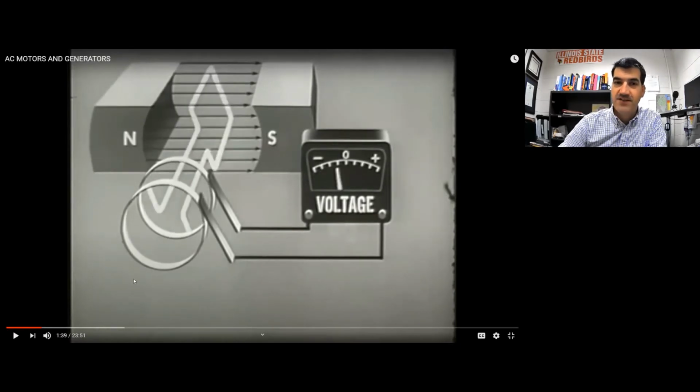All right, I'm going to pause it right there. It's kind of hard to notice, but if you think back to the hand crank generator that I showed earlier, here is the coil of wire, otherwise known as the armature. And this coil of wire is directly connected to these slip rings. These are called slip rings. And what I want to point out here is that these slip rings are actually rotating with the armature.